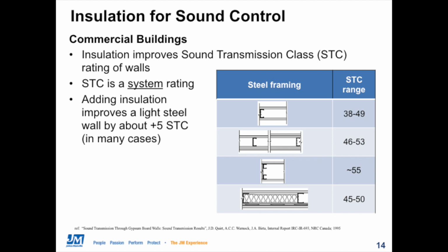STC is usually measured in the lab, but it can also be measured in the field by an acoustical consultant. So STC ratings are really important because this measures how well the wall is going to deliver privacy between spaces like offices, hotel rooms, or apartments, and also for creating quiet environments in schools and hospitals. It's really important to point out that STC ratings only apply to the entire system, whether that's a wall or a floor ceiling, not to individual products.